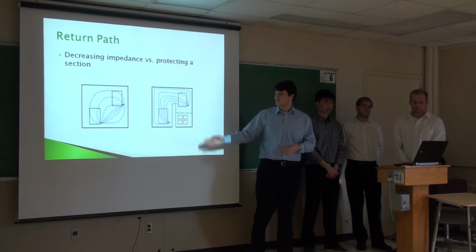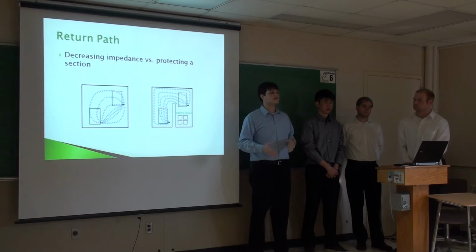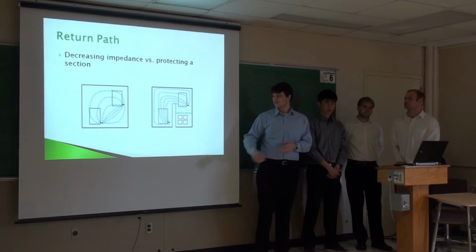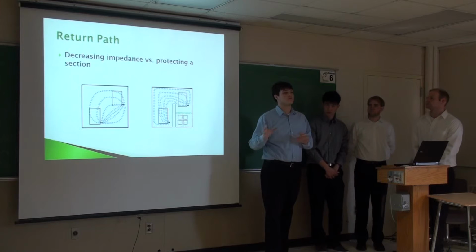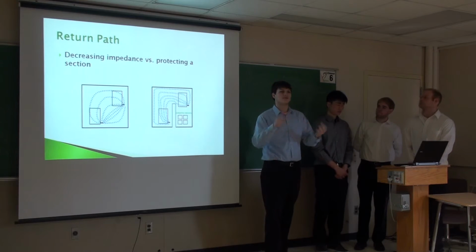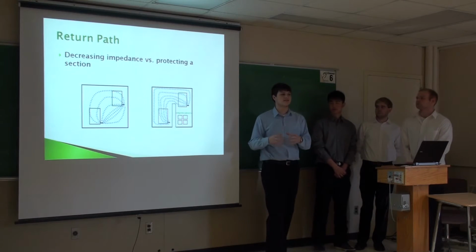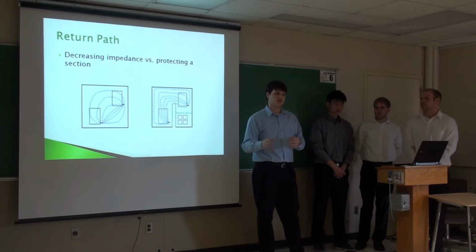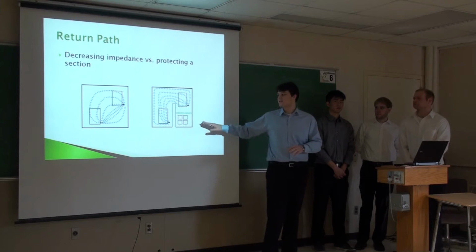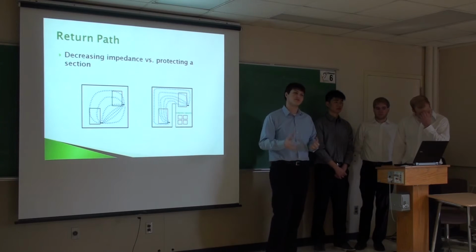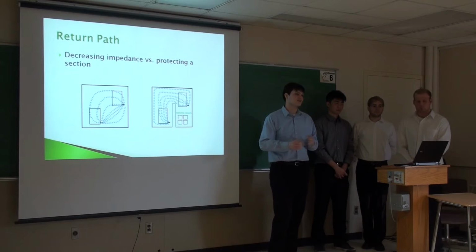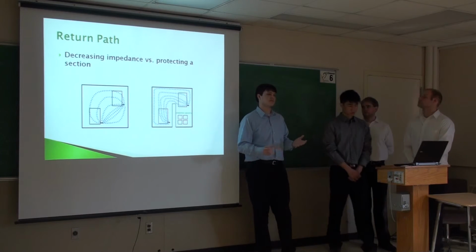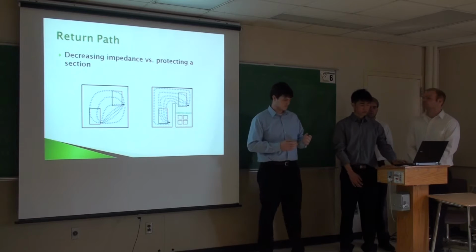So one option is to cut this little path here. What that does is it says that no current can flow through there, since the impedance is roughly infinity. So as the current talks back and forth between components A and B, all of it's forced around this cutout, and it leaves that sensitive area untouched by that current. So it increases the impedance between A and B, which lowers the performance there, but it isolates your sensitive circuits, which helps increase that performance. So as you'll see in printed circuit board design, everything's kind of a trade-off. You give up performance somewhere to gain performance somewhere else.